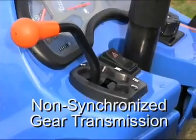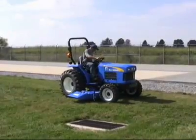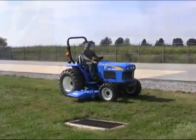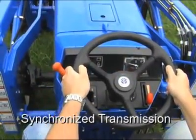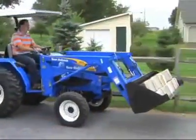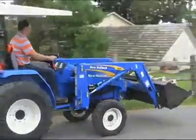The most basic option is a non-synchronized gear transmission. This simple, rugged system is built with straight-cut gears that spin freely. This design requires the operator to stop the tractor before changing gears. The alternative is a synchronized transmission, which is built with helical cut gears that are constantly meshed. This makes shifting easier and allows the operator to change gears while the tractor is in motion.